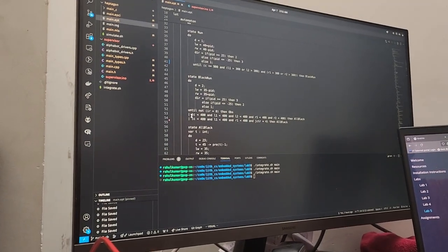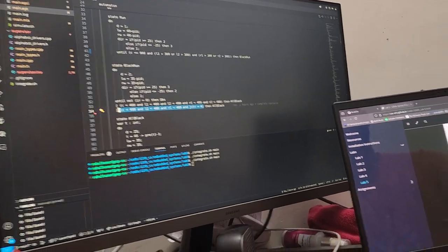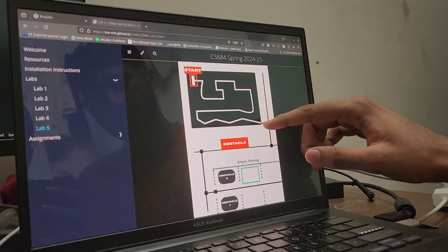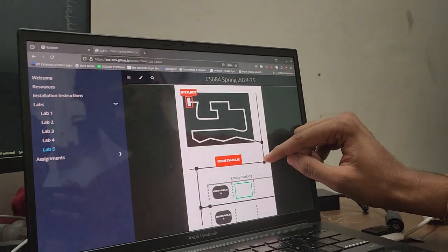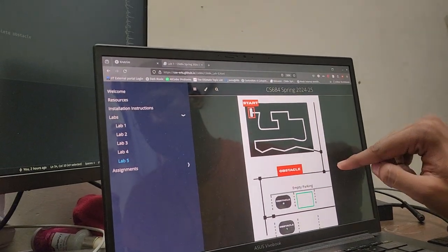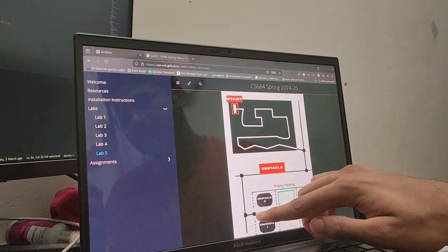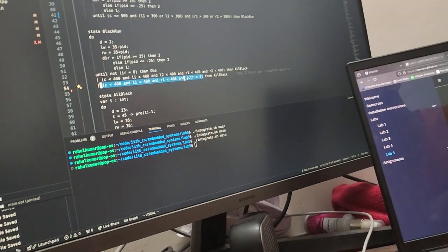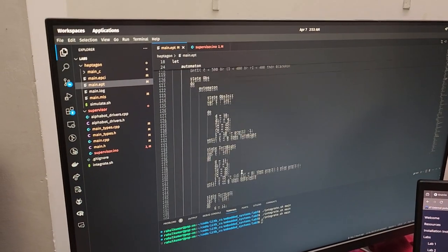Coming over here, I said I will explain this. As you can see, these are different conditions. So why have we used this? If you see all these 4 junctions, there are horizontal lines, it's not just a straight line, so the extreme sensors also detect the black line. Here the sensors are aligned like this and the board will be facing this way. All the extremes will be here also, but here the line is only straight, so the extreme sensors do not detect a value. So when we are on the parking side, we do not include the R1, R2, L1, L2 values.